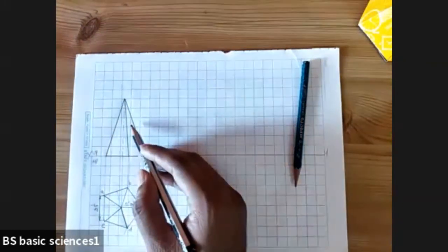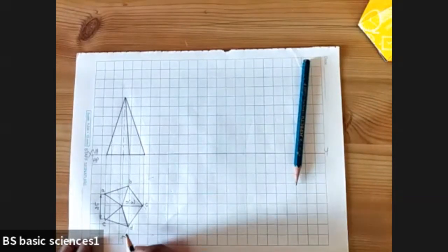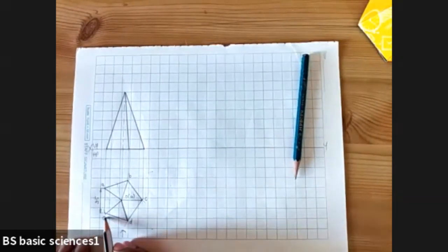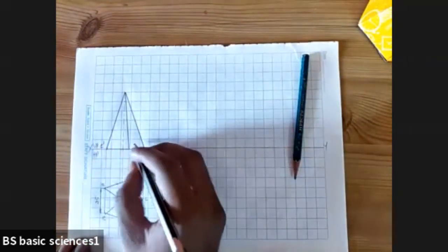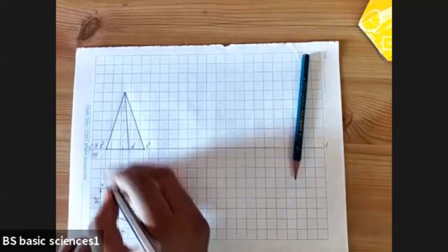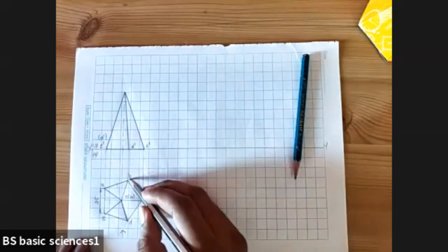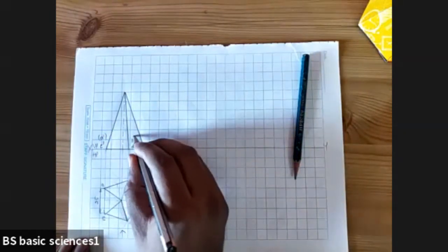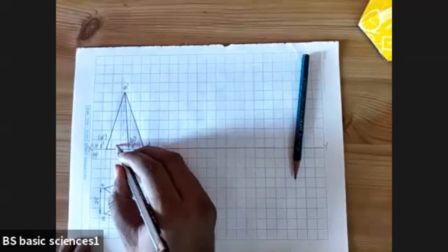Now to mark the points. In this condition, what do you do? The observer will be looking from this side. So when he is looking from this side, he can see the points E, D, and C. The corners E, D, and C are visible to the observer. That is why these points will be E dash, D dash, and C dash. Behind E we have A dash, which will be in bracket. Similarly, behind D we have the point B, so it will be B dash, in bracket. And what about the axis? This will be my O dash, and this will be O1 dash, in bracket.